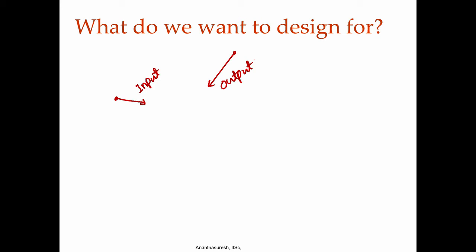That is what we had done. With regard to other design methods, it was different, but everywhere we had this notion that input given in one direction, we have desired outputs, or rather target output. We choose the point, if this is the input point, output point, we want this. So, can we get this? Now, you can see how that instant center of rotation concept could apply, because we have 2 points. Here is the point 1, which is the input, we have point 2, and we know how they should move